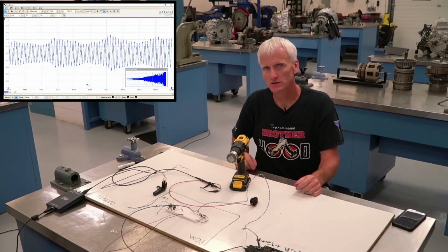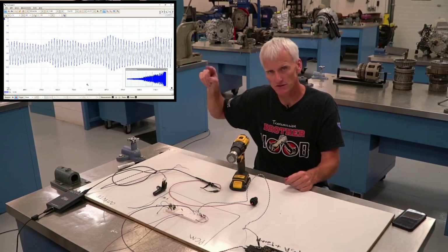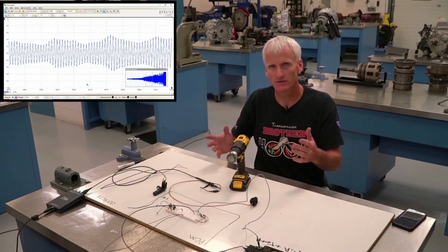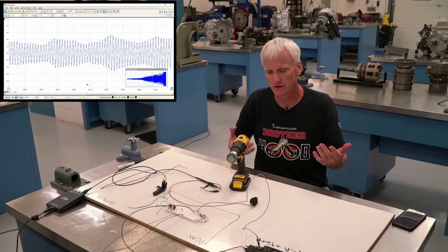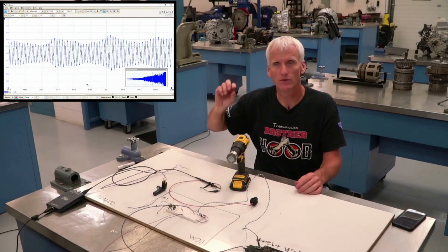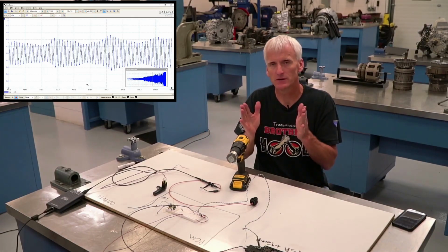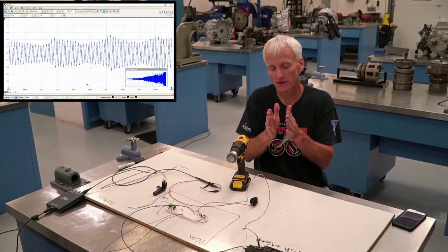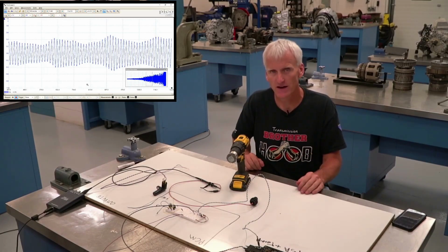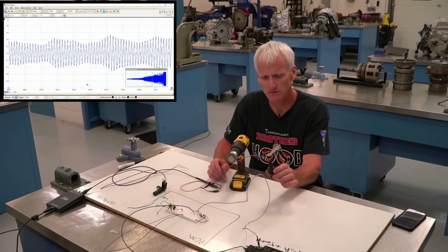So what a computer is going to do is count, in a period of time, how often those signals switch, and based on that, it can figure out how fast something is spinning. If you imagine every time the voltage goes above, let's say, half a volt, it counts it: 1, 2, 3, 4, 5. Then it looks at that across a period of time, or at least looks at how close together they are happening, and it can figure out how fast that part is spinning. So that's a variable reluctance type speed sensor, 2 wires.